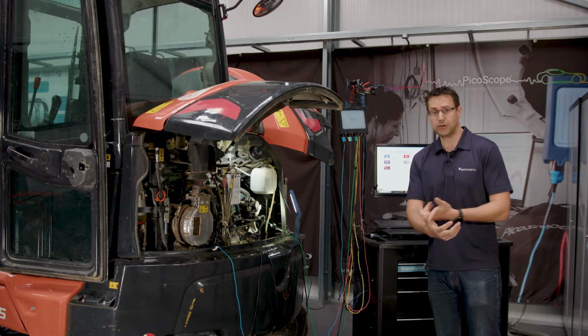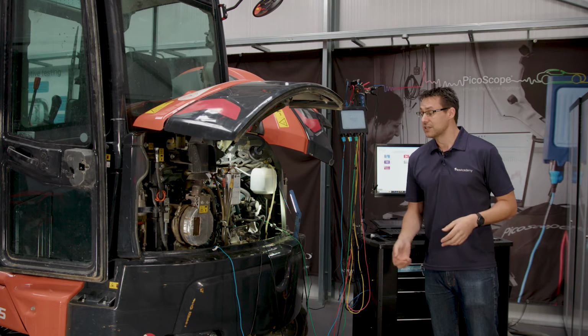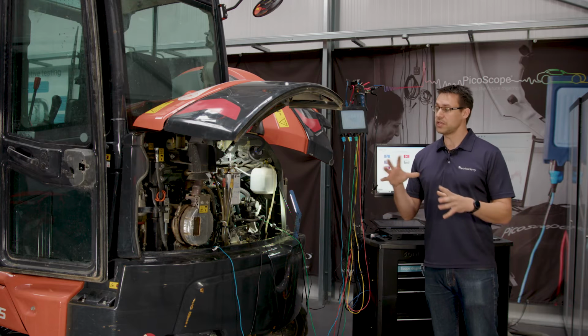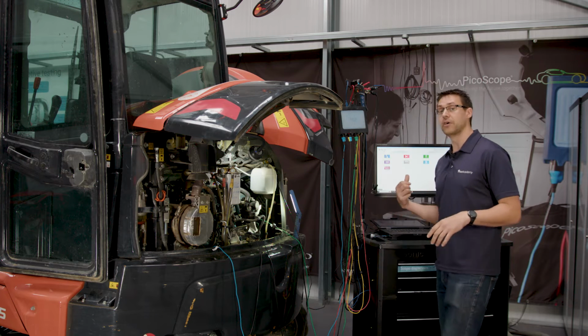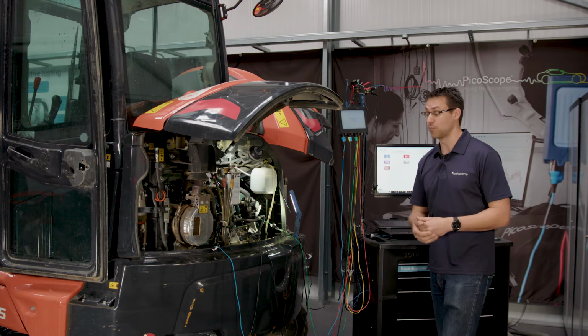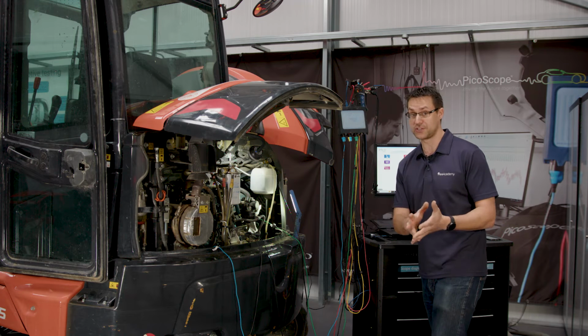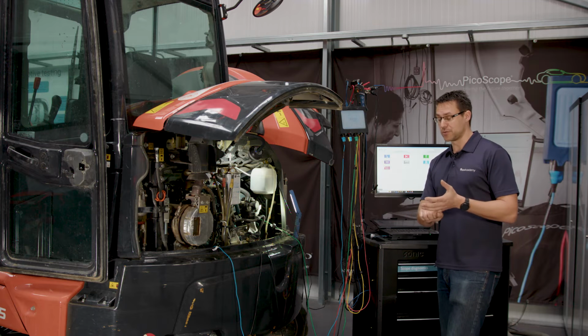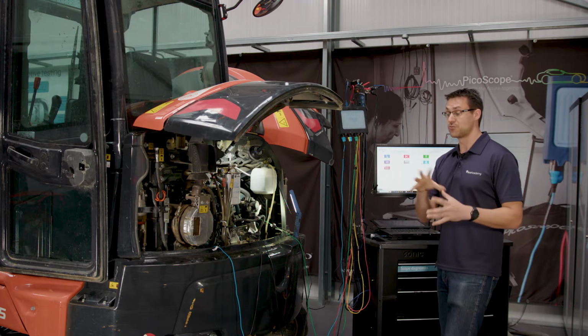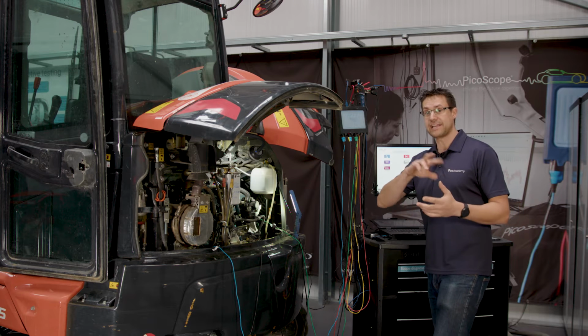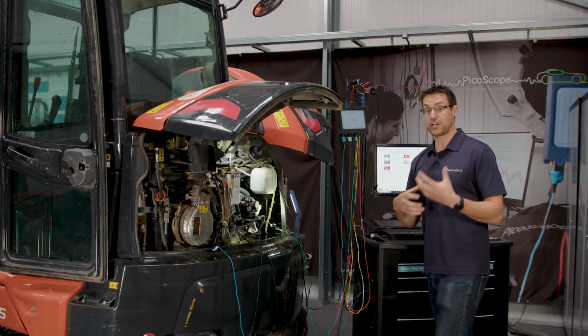So there was no fault codes, no warnings on the dash. What we were looking at then was, right, can we manipulate some of the signals we see and show them in a way on Pico about what the engine's actually doing? One of those is with the crankshaft sensor. In a couple of videos, obviously, and a lot on the forum, we talk about something called crank maths. Crank maths is really important with showing the analog output of the crankshaft sensor.